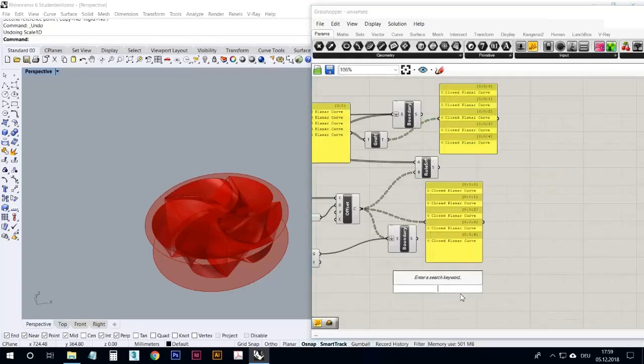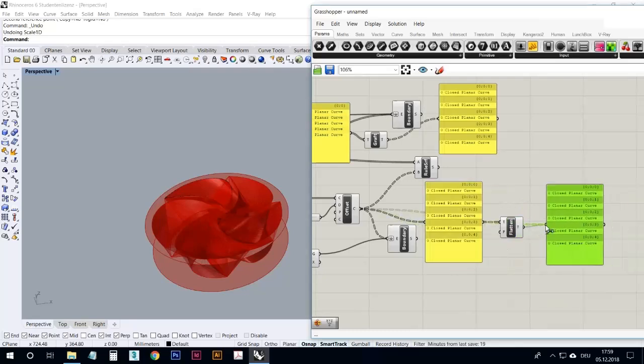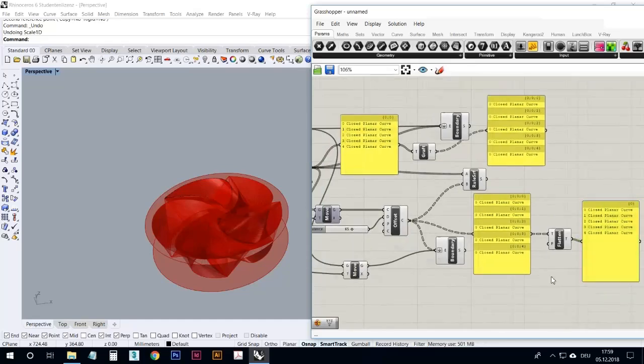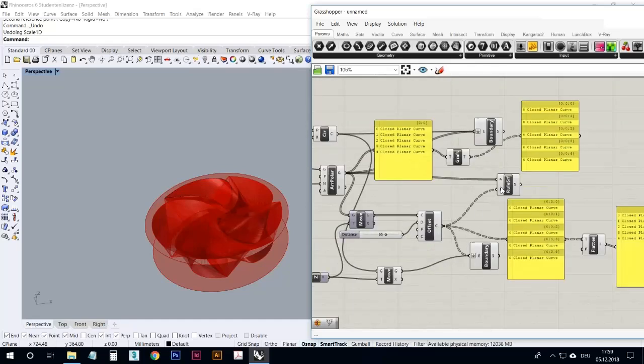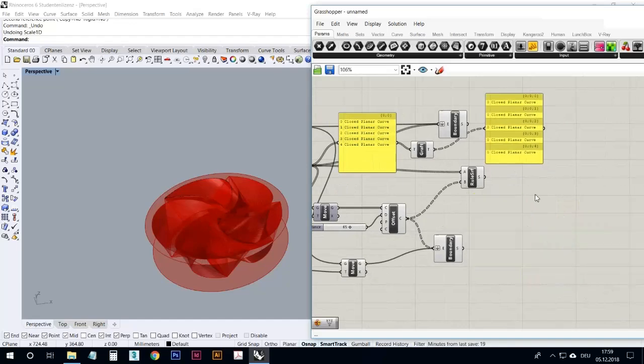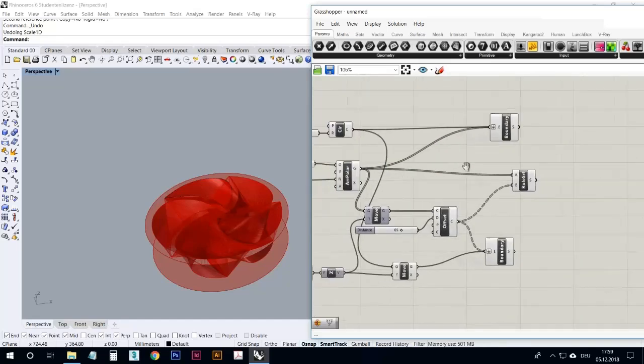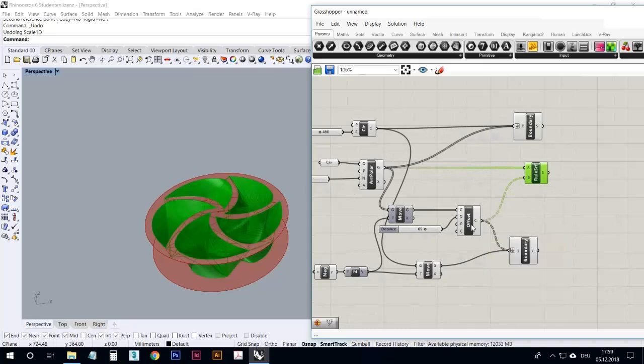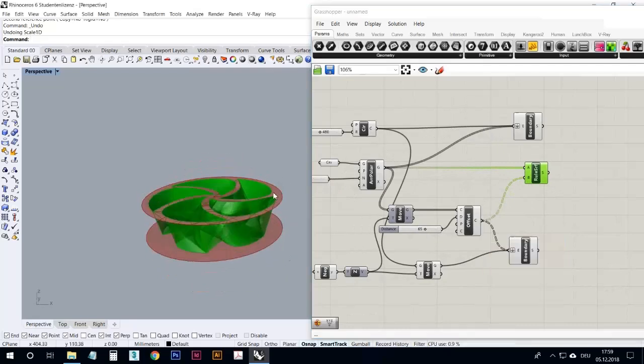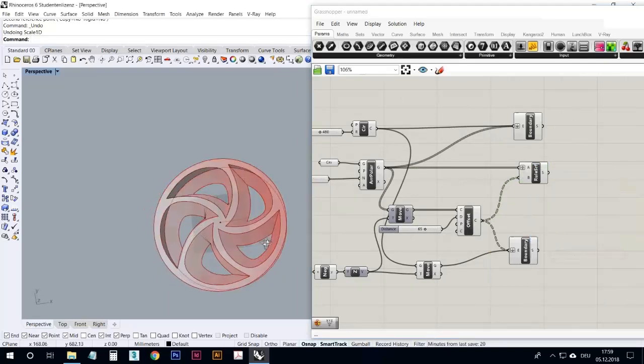The other way around, if you flatten the tree, it looks like a chopped-off tree there. You can look at this list, copy the viewer, and look at the list. Then you see that you can also make this work by flattening the B input if you want to. So you can do it either way. I hope you can follow that one. Graft and flatten are list modifications, which are very essential when you're working with Grasshopper. So if I graft this A input, we have the result we want to have.